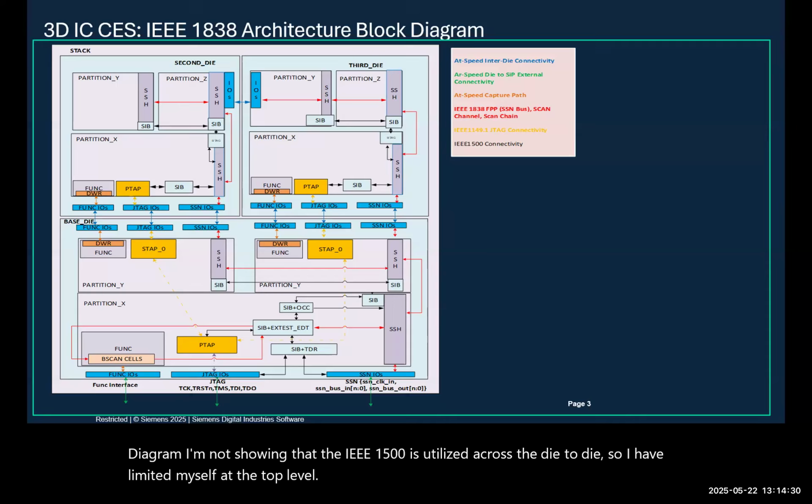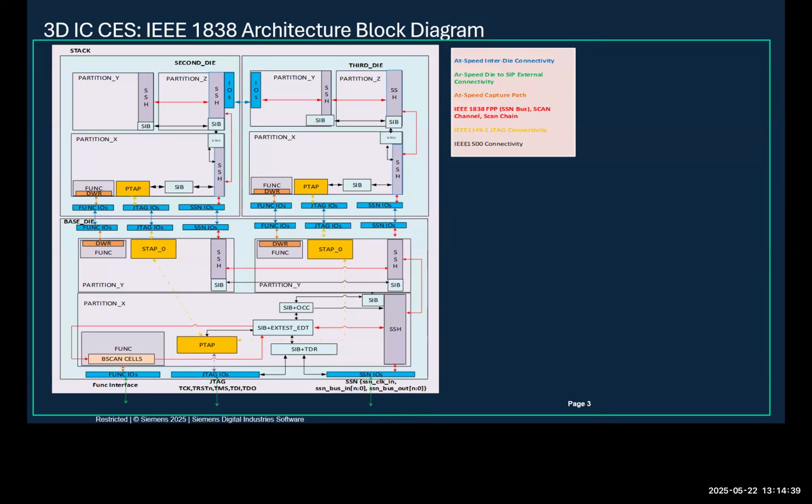What is the expectation for dies for chip? Actually, I don't even know what to call this. Basically, chiplet systems that use HBM3, and HBM3 comes with IEEE 1500 ports, right? Are those ports expected to be exported at the package level, or are those ports connected to the ASIC, and then basically all the testing of the HBM happens through the ASIC?